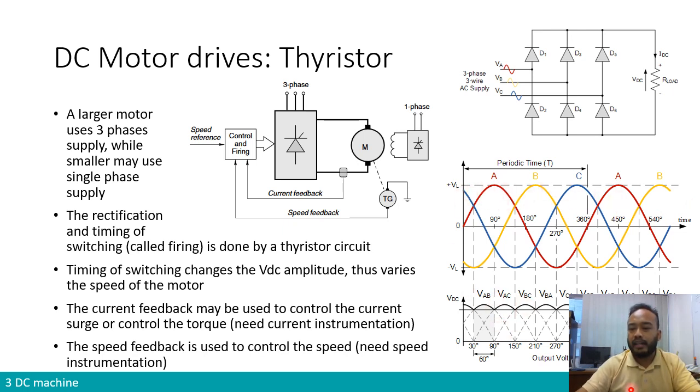So at the end, we will have basically the output of the diode circuit, the rectification circuit, the rectifier. The output waveform is going to be like this. Okay, so that is if we employ a diode. But of course, employing a diode means we would only have this DC voltage. So we can see there is a pulsation of the output voltage. Therefore, we will basically not have the maximum VDC at the end, the voltage that is viewed from the point of view of the motor.